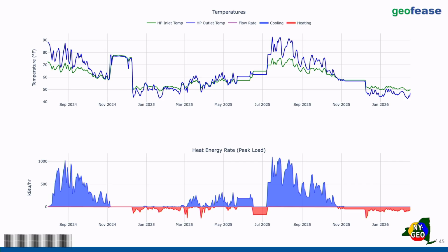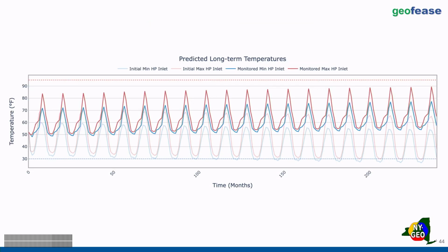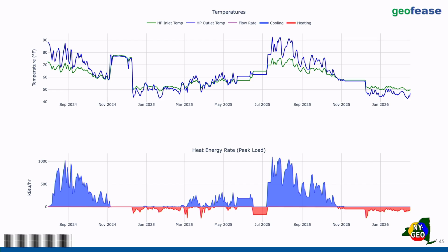Yeah, great question. The main difference is unexpected auxiliary backup usage. And I think Isabel touched on that a little bit in the Eversource project. It happens a lot, especially on these hybrid systems. Designers have good intentions with hybrid systems, but when a building operator gets their hands on the system, unless there are governors in place to limit backup usage, it tends to be run more than expected. So that's what we see a lot in the wild: these hybrid systems tend to not be the percentages that the designer had intended when they designed the system. So good question though.